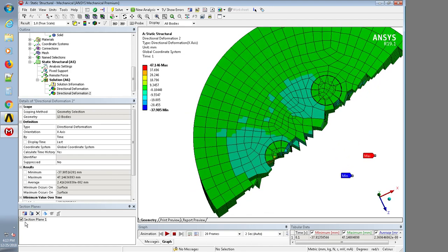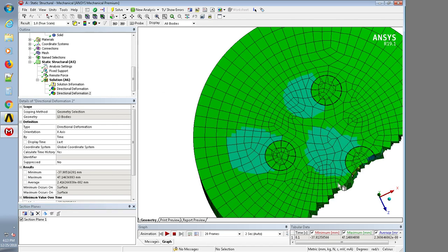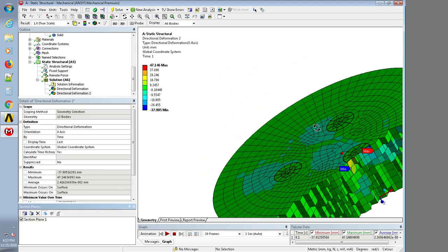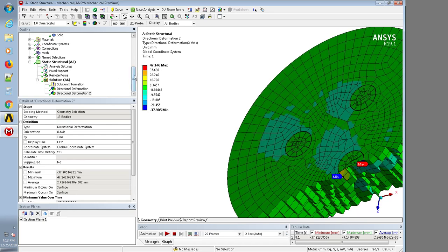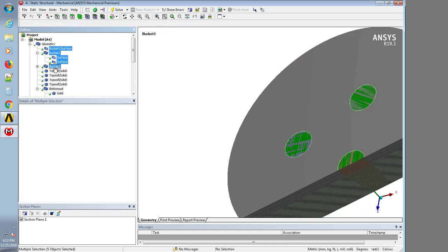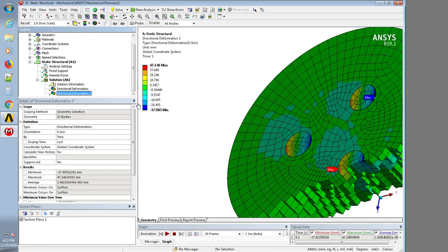And so let me bring this back, this section, click on the section, click on edit, bring it back to where the min and max values are, around here, looks like. So turn off the editing to make rotation of this easier, and potentially turn off some buckets just to look at the soil. So F9 to hide, and back into the deformations.